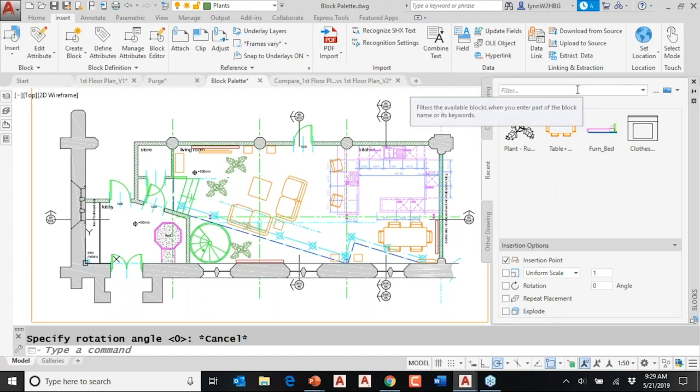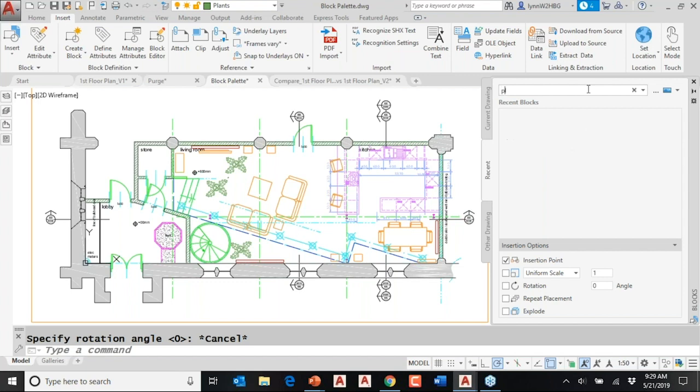these, there are filters. And it's the old-fashioned filter, by the way. Hopefully you know your asterisk. So if I wanted everything that started with the word plant, let's backspace, plant. I want you to see nothing shows up unless it actually is the word plant until I put that asterisk there. So then it would show me all the blocks that started with the word plant.